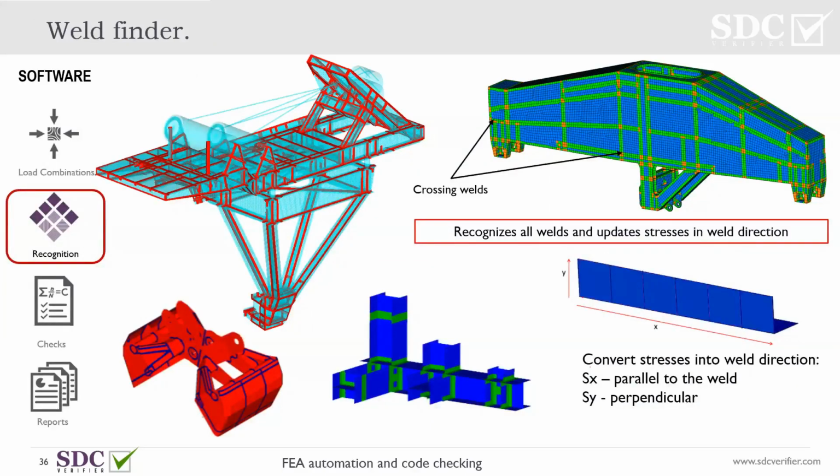Of course, it does something more for you, because the background idea of the stresses for fatigue is more complex when it comes to the finite element modeling approach. By default, you receive stresses related to the local element coordinate system, which sometimes can be quite chaotic, right? So you could get things messed up.